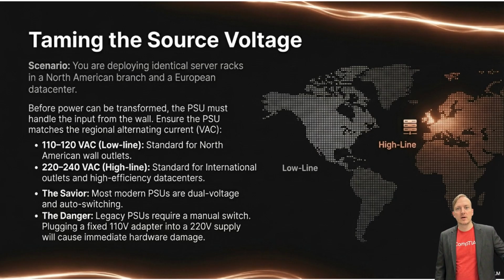The savior here is that most modern PSUs are dual voltage and will auto-switch. The danger? Legacy PSUs require you to flip a manual switch. If you plug a fixed 110-volt adapter into a 220-volt supply, you will cause immediate, catastrophic hardware damage.